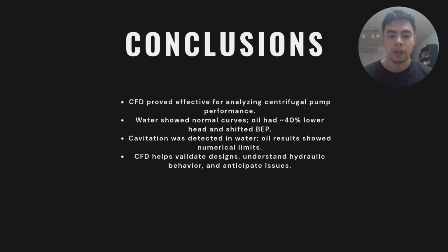We also analyzed cavitation. For water, small low-pressure zones on the suction side of the impeller indicate the beginning of cavitation, while for oil, the results show negative pressures, which were numerical effects. Overall, CFD proved to be a powerful tool to validate pump performance, understand internal hydraulic behavior, and anticipate problems such as cavitation without relying only on physical testing.